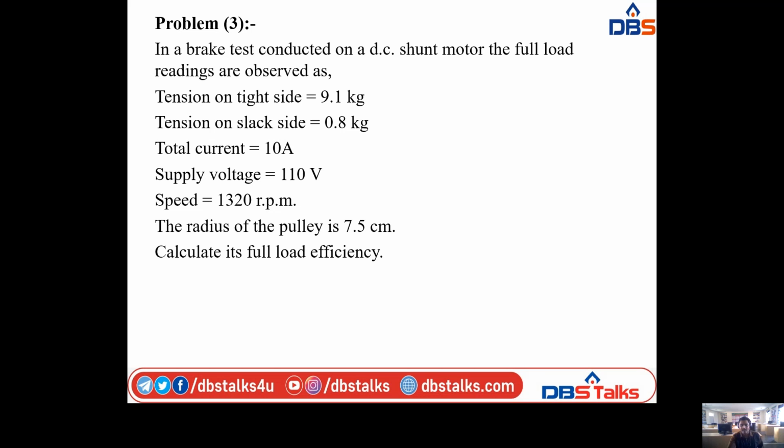From this diagram, I1, that is the motor input current, is 40 amperes and V is equal to voltage across armature, that is 200 volts, and I2 is equal to load current, that is 32 amperes. On the generator side we have this load current is 32 amperes, and voltage across the generator is 160 volts, and RA and RSC, that is armature resistance and field resistance of each machine.